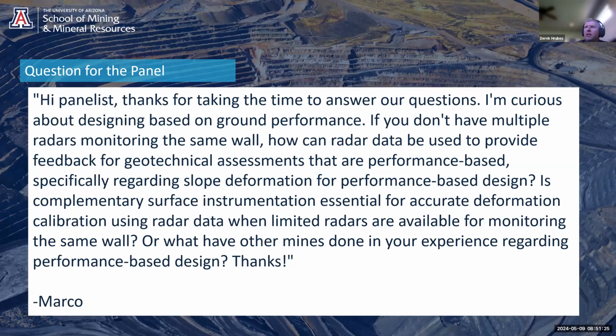I would also add that if you're using multiple technologies, which we would definitely advocate, you may have different thresholds for those different types of monitoring systems. What's applicable for a radar unit may not be applicable for a prism, given the vector of movement. So it's important to have an appreciation of the overall slope movements and rates, but also how those translate to the various types of instrumentation, and how you might end up actually alarming on each of those types of instrumentation, if that's the end result.